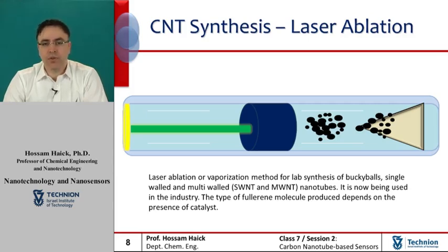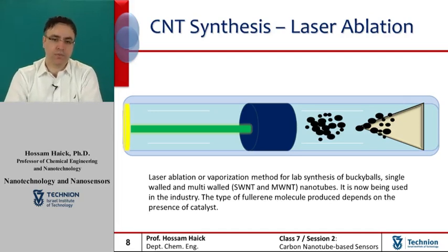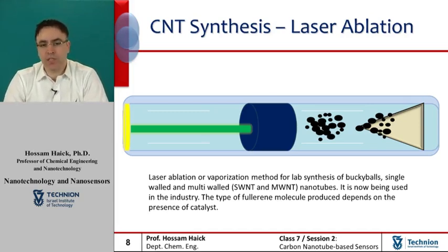A laser beam focused on the pellet vaporizes graphite by scanning its surface so as to maintain a flat and uniform surface. The carbon species produced by the sublimation of graphite are displaced by the gas flow, coalesce in the gas phase, and finally deposit on the cold copper collector.